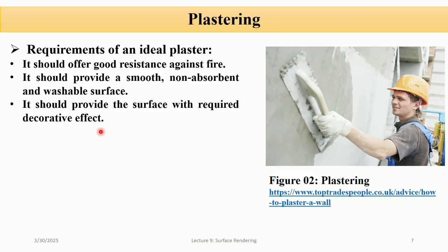The purpose of providing plastering is to provide an even, smooth, regular, clean, and durable finish, to protect the surface from the effect of weathering agencies, to conceal defective workmanship, to cover inferior quality of material used in the masonry, and to provide a smooth base for decorative surface finishes.